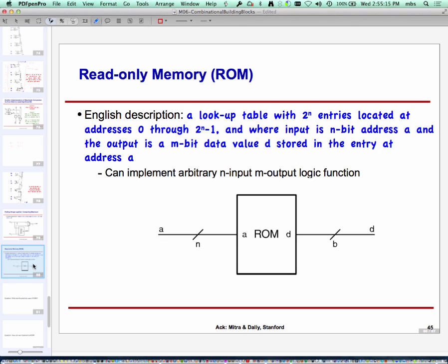So a ROM implements a function. It takes as its input the address, it spits out as an output the content of that address. Another term that people in CS like to use is lookup table. I have a table, I tell the lookup table which row I am interested in, and it gives me the value in that row, that mailbox.